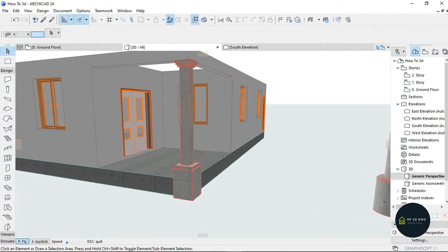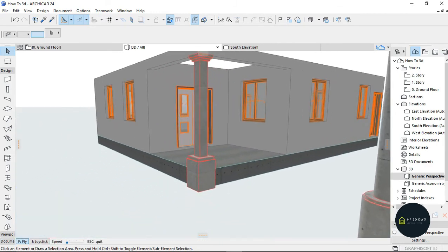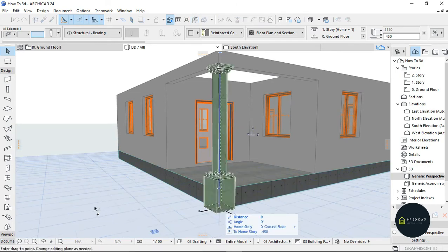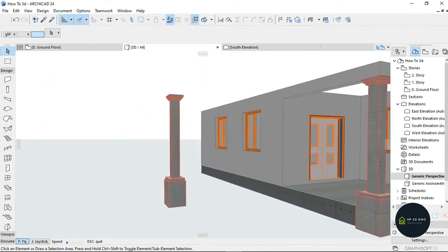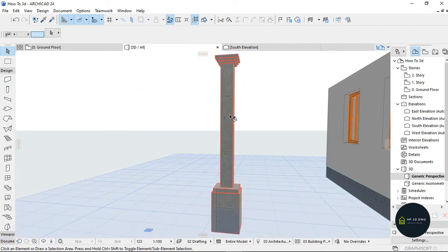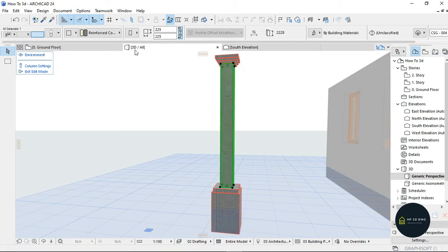And what you want to do is select this part that you want to be slanted. For purposes of this video, let me create two of these, or copy this, maybe somewhere there. So to make this particular pillar slanted, that's the middle part, you click on it and click edit, then click the particular one that you want to make slanted, click on this cross section size, and select this tapered size.